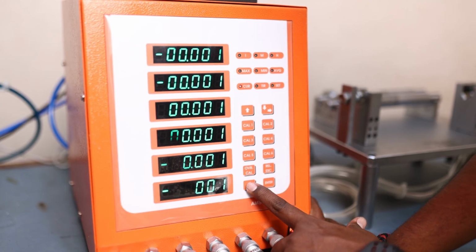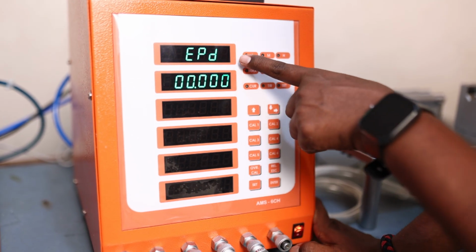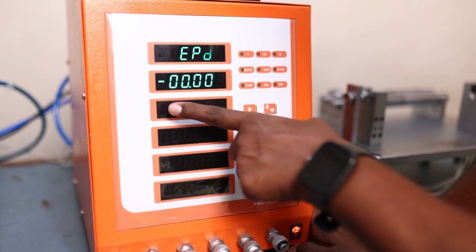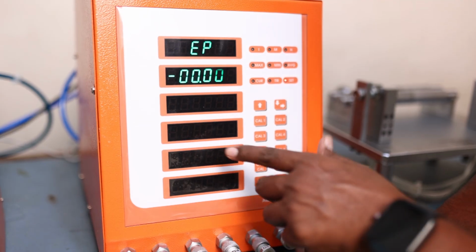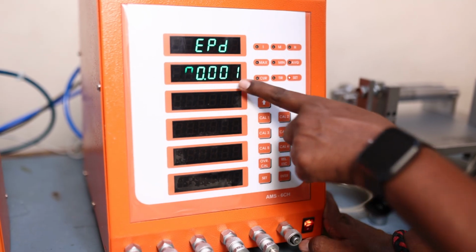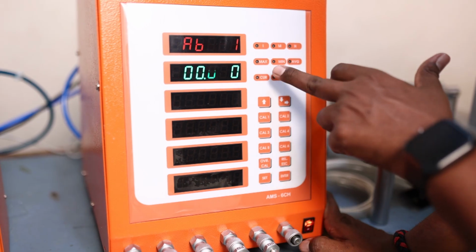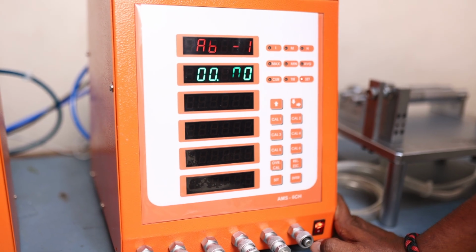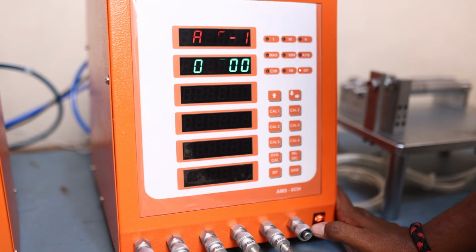Now by pressing the set key it will ask for the enter password option. Using the up arrow key or down arrow key, you have to enter the password that you set for the particular program number and function number, and press enter. If you enter that, it will ask for ABS value, USL value, LSL value, high and low master values and ovality value for all the channels.